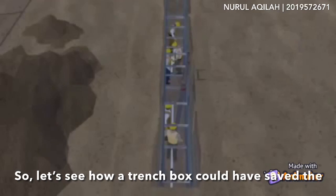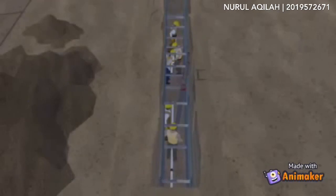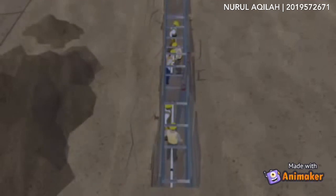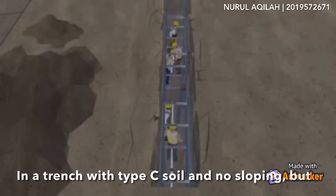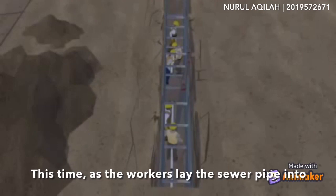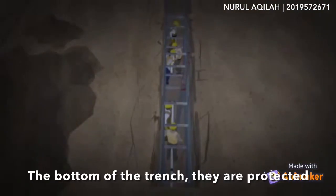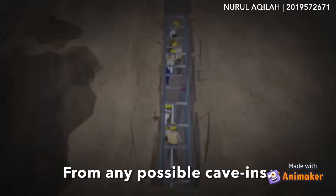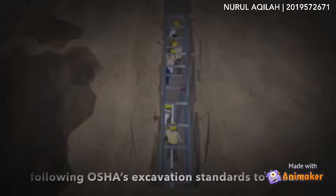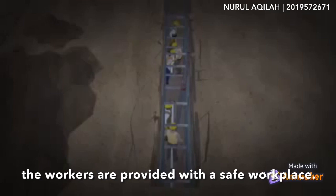So let's see how a trench box could save the workers we saw at the beginning of the video. For our example, we will assume that the workers are in a trench with Type C soil and no sloping, but the workers are inside a trench box. This time, workers lay the sewer pipe into the bottom of the trench. They are protected from any possible caving. This example shows the importance of employers following OSHA excavation standards to ensure the workers are provided with a safe workplace.